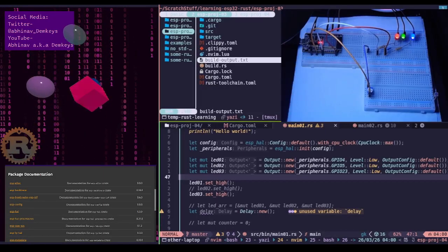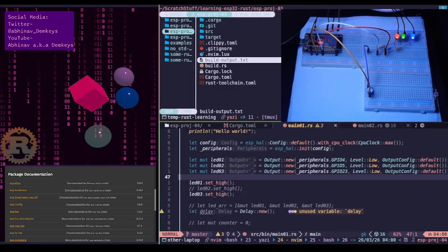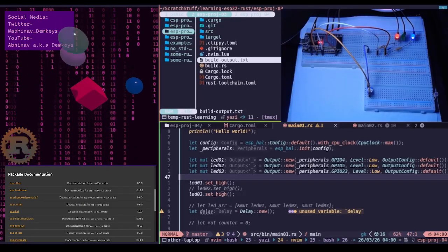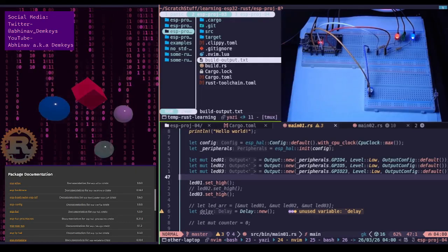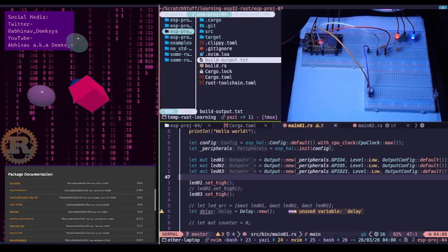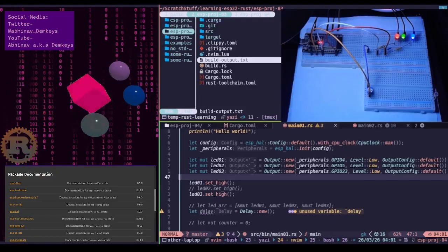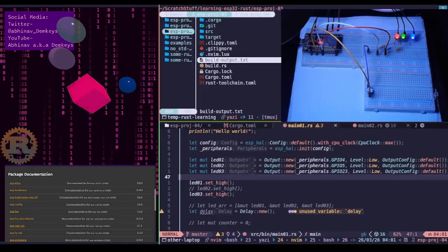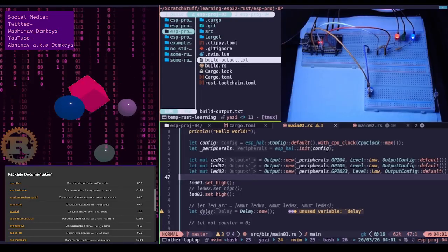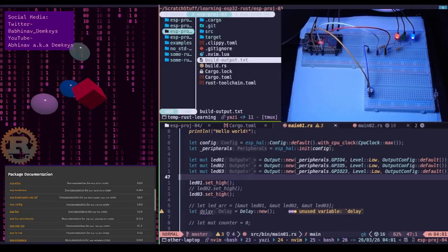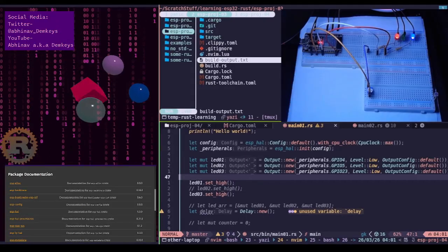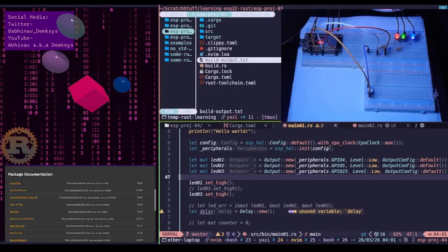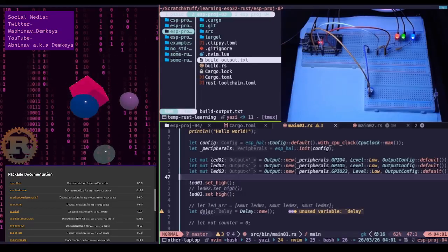Okay, assessing circuit safety. All right, this is a classic setup, but with the ESP32, there are a few gotchas that can mean the difference between a working project and a puff of blue smoke. The short answer: it is safe as long as VCC is 3.3 volts. If you connect that VCC pin to a 5-volt rail, often labeled VIN or 5V on dev boards, you are risking frying the ADC pin. Oh, the ADC. Okay, okay. Yeah.